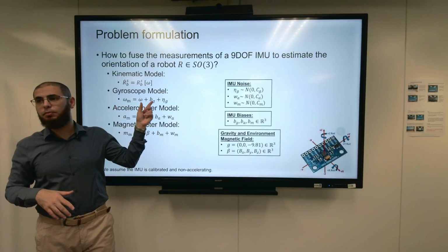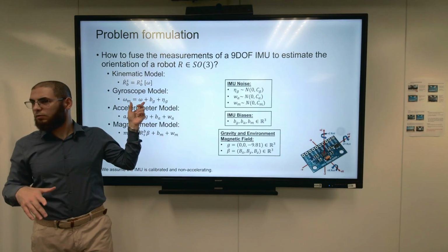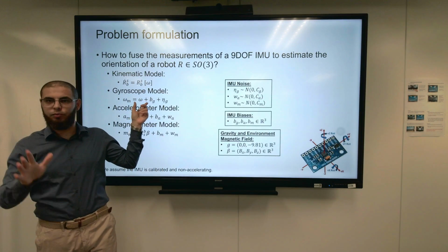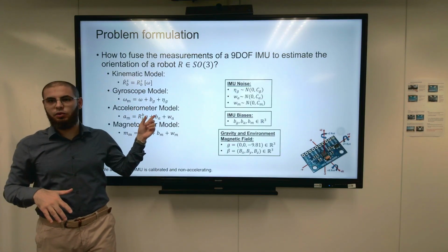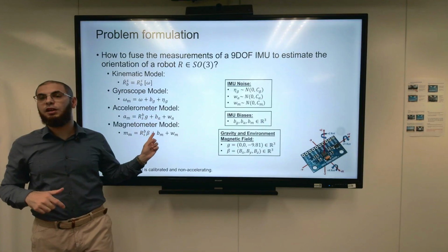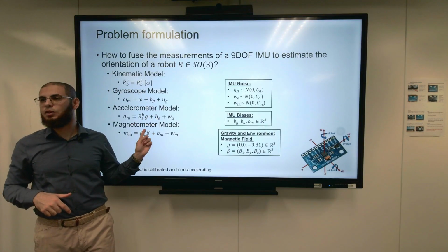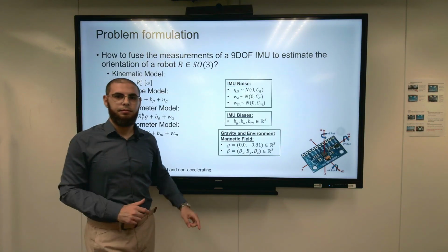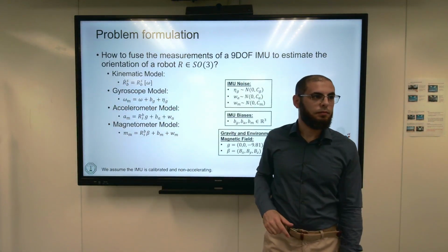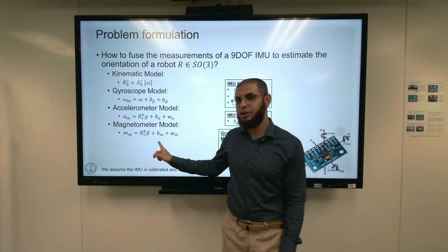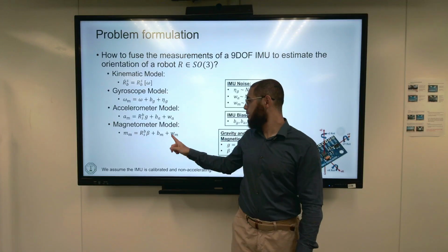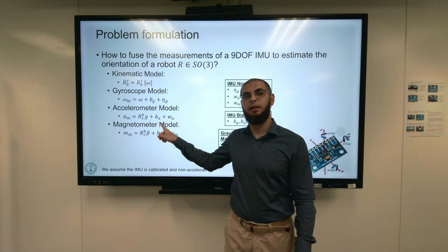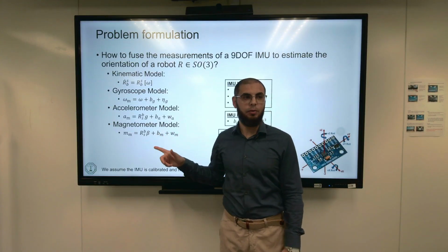The gyroscope bias is really not that important. Okay? You can actually assume it's 0 by doing proper calibration. The accelerometer, you can also assume it's 0. The magnetometer is the one that's really very important. Why is that? Does anyone remember why? A lot of things affected it. Does anyone remember what was the experiment we did in the class here to actually demonstrate that the bias gets changed, of the magnetometer especially?